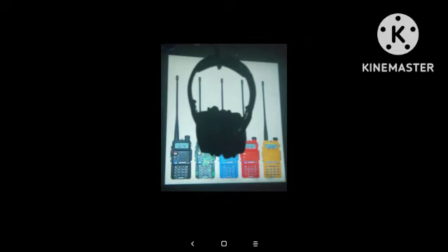Number 30. What is one reason a triode vacuum tube might be used instead of a transistor in a circuit? It may be able to handle higher power. Number 31. The drain of a field effect transistor corresponds to the blank of a bipolar transistor.